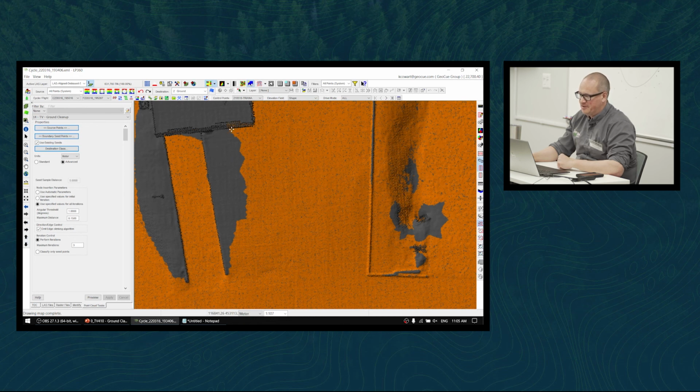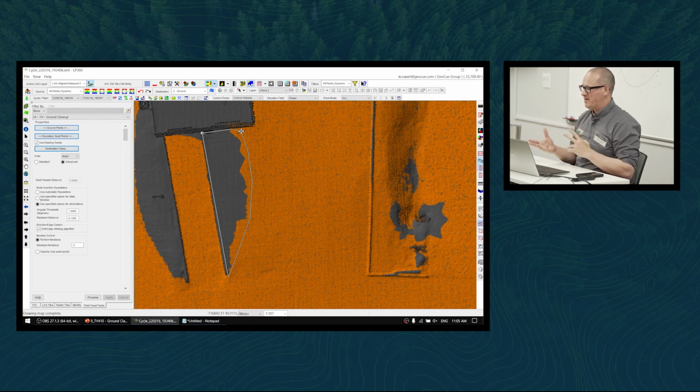For example, with this one, I'm going to start left clicking and very crudely outline this shape like this. It doesn't have to be super precise, just encircle the shape that you want. One thing to remember about this task is that it has an undo function, but it only goes up to 500,000 points. So you want to do it in small chunks. That way you have that undo function available, and if you mess something up, it's not a huge waste of time.